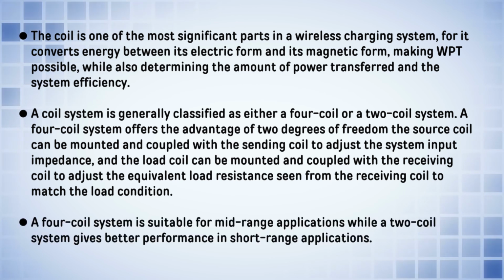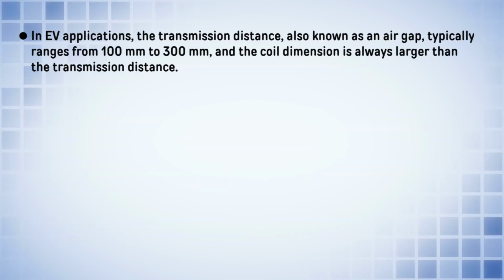However, on the other side, we have soft switching resonant converters, and they are categorized depending on whether we are going for zero voltage switching or zero current switching. These ZCS and ZVS are helping to reduce the switching losses significantly. That is why DC-DC converter people are controlling in ZCS and ZVS mode, where during transition, suppose I